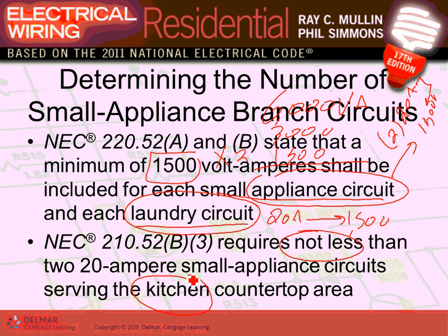There are 3 circuits in the NEC code book, guys, called sacred cows. One set is the 2 circuits in the kitchen. In the kitchen, they give you 2 20 amp circuits that cannot feed anything other than the kitchen and dining room. In the bathroom, one circuit. That's a sacred cow; it cannot feed anything else. These are dedicated circuits. Done. It has nothing to do with the 4 circuits that we calculated. Two for the kitchen, one for the laundry, and one for the bathroom.